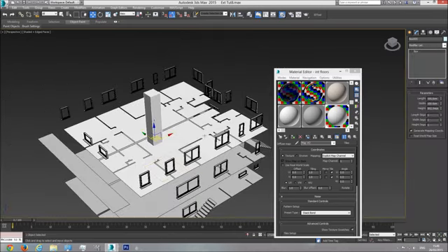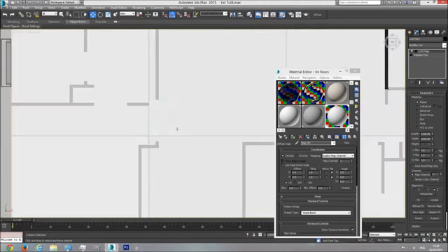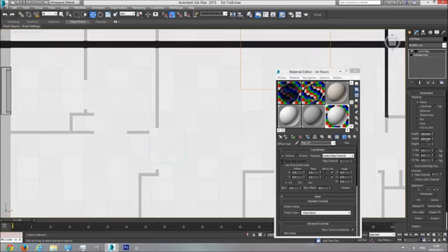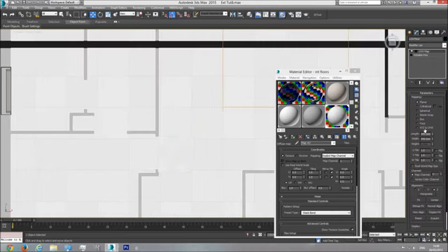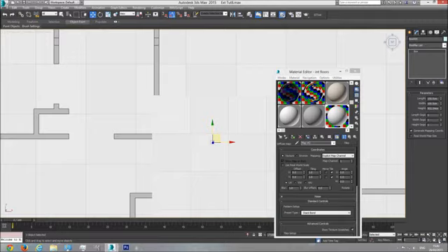So let's delete this UV map. I'm going to go back to the floor, go back to top, and let's make it much smaller. It needs to be like this square. So I'm going to take this down to 250 and 250. Now the alignment is too small, so let's make it a little bit bigger. 350 over 350. A little bit more, 400, 400. That's fine. So now it's 100 centimeters over 100 centimeters tile, which is great.